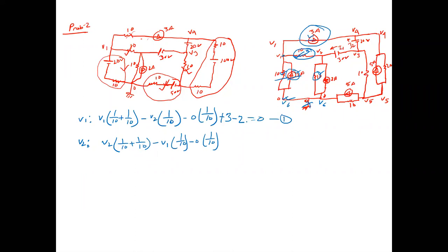The resistance part is finished. Now the current. This current, outgoing means plus, incoming means minus. This is outgoing. Outgoing means plus, so plus 2. Another current is incoming. Incoming means minus. So minus I1.